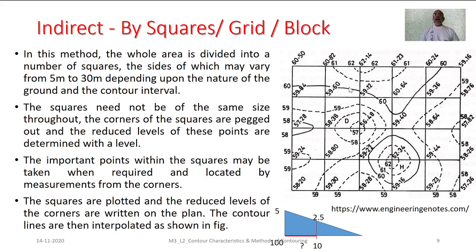Now, as we come to the office, we will be reproducing this particular network of survey lines with reference to the actual meridian, and accordingly by following a certain scale we will have each of these particular sections defined on the drawing sheet that we wish to prepare in the form of that particular contour map. So at each of these sections, the way you see, we can diagonally write all those reduced levels.